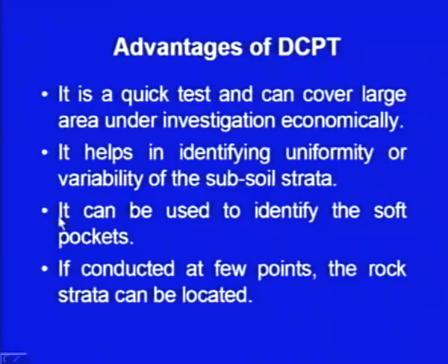The third advantage is that it can be used to identify the soft pockets, because it is a very quick test, very cheap test, and it can economically be used to identify where the soft pocket occurs. You have to do the test, and if all of a sudden there is a decrease in the resistance, that means there is a soft pocket. If conducted at few points, the rock strata can be located.